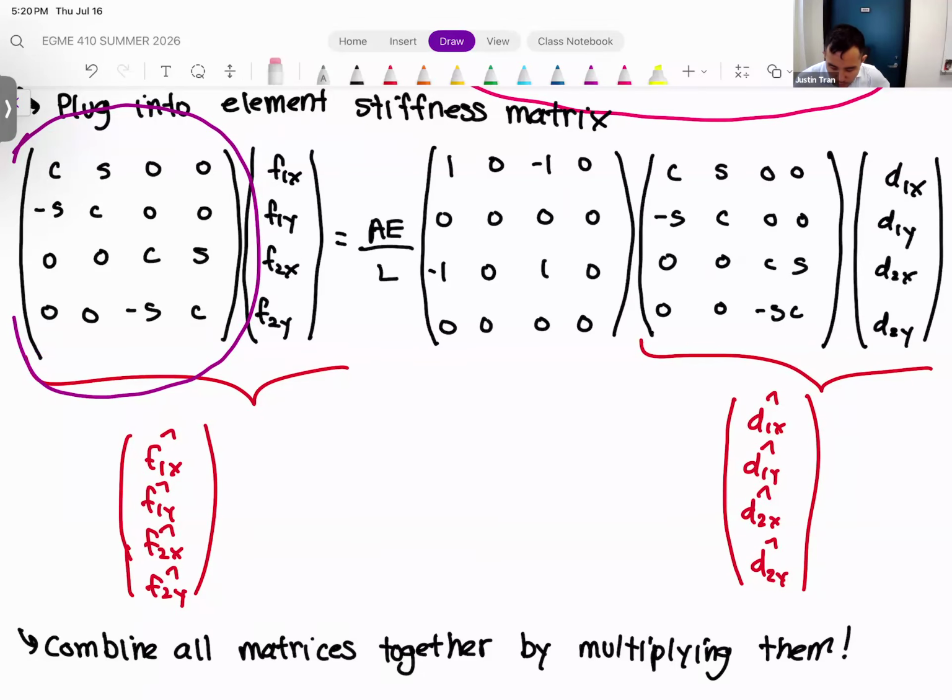Normally when you move a matrix from one side of the equation to another, if you remember from your linear algebra class, that involves multiplying by the inverse, which, if there's anything more annoying than doing matrix multiplications, it's finding a matrix inverse, especially for a 4x4 matrix. But we're in luck, because these transformation matrices have the property that the inverse of the matrix is actually just the transpose. So you just have to take the transpose of the matrix. That gives you the inverse.